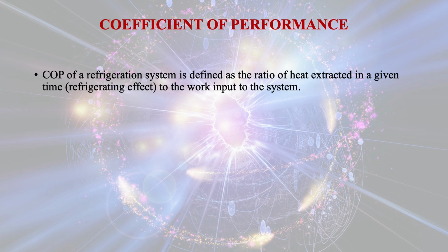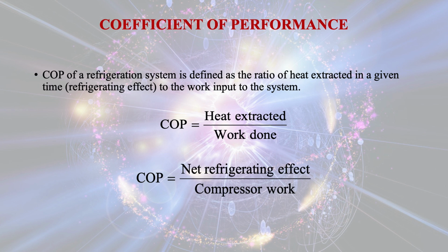Coefficient of performance, in short we will say COP. The COP of a refrigeration system is defined as the ratio of heat extracted in a given time, that is known as the refrigeration effect, to the work input to the system. So, coefficient of performance is equal to heat extracted divided by work done. We can also say COP is equal to net refrigerating effect divided by compressor work.